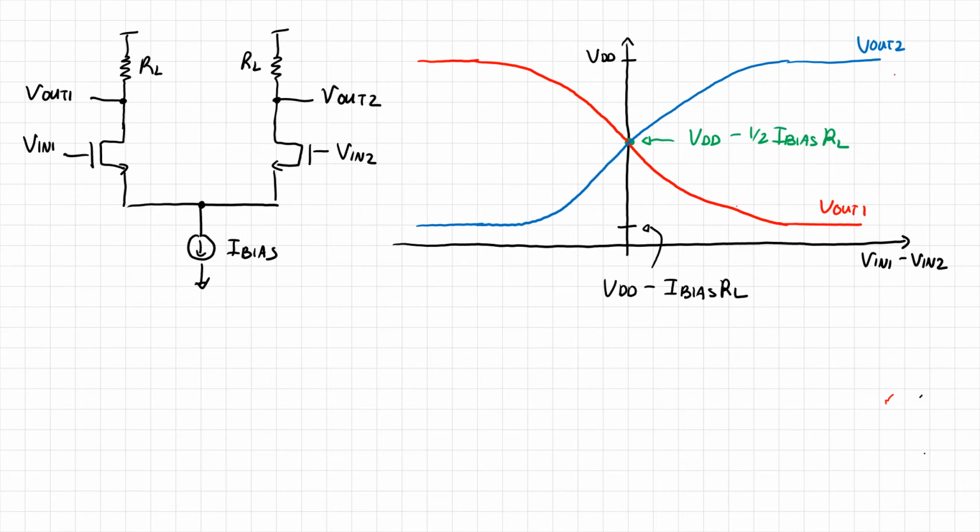All right, so what we often like to do when we talk about a differential amplifier is we like to separate the input signal into a differential mode signal and a common mode signal. We do that with the following kind of circuit representation. We say that we have some common mode signal, VCM, on top of which we build a differential mode signal.